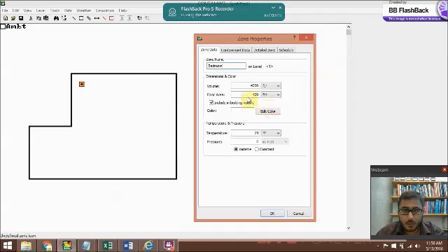Once this is done, make sure you click include the building volume over here, because that would determine your floor area and it would calculate based on your volumes. So even though we're modeling, in our case, one room within a larger building, we think of this as the building. You could model hallways or other parts including this, and have data separated for both spaces. You can take out results for just one space you want.